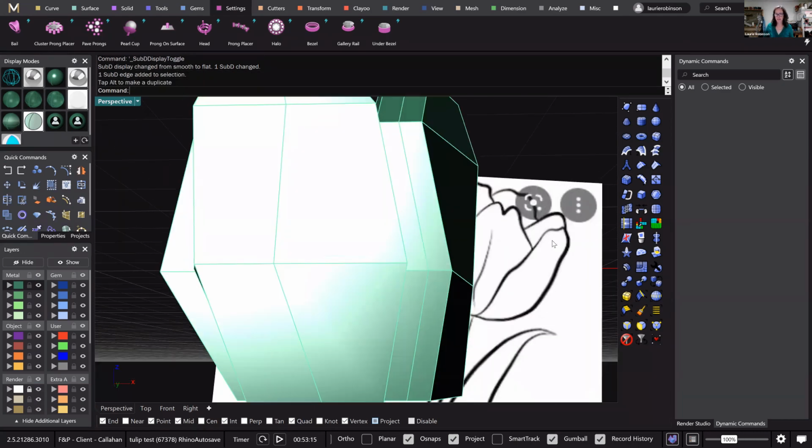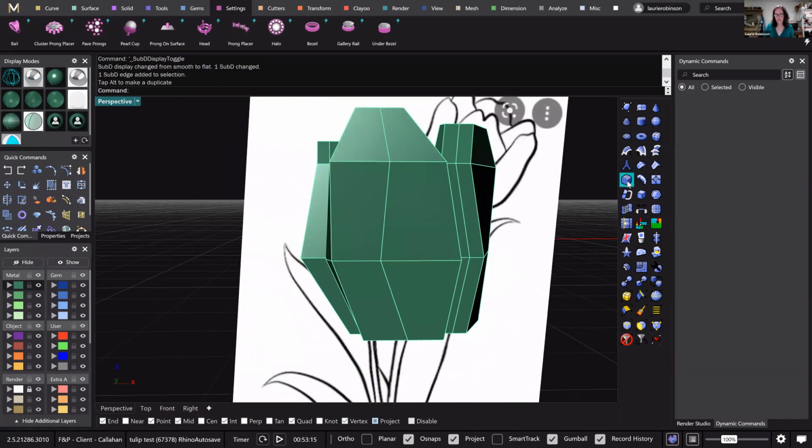Okay. And now I will add a bevel. So in order to push that edge in, I'm going to create 2 edges right alongside it that will keep the rest of the surface on the plane that it's on now. So that command is right here, sorry. And I'm just going to select these 2 edges because I don't need the whole ring to be selected.